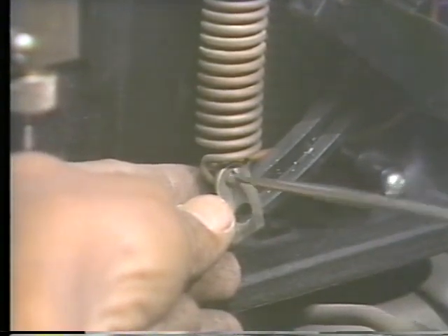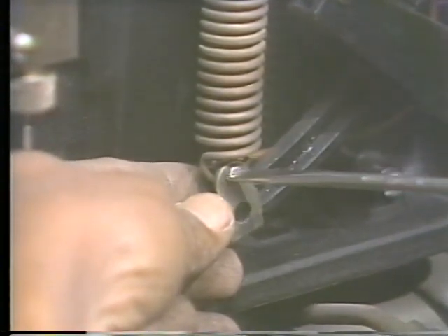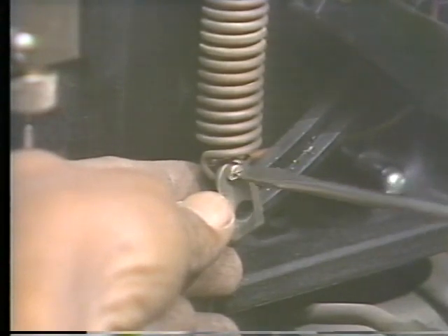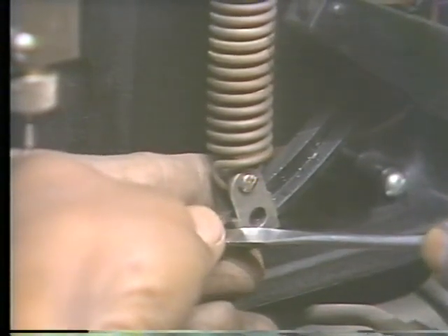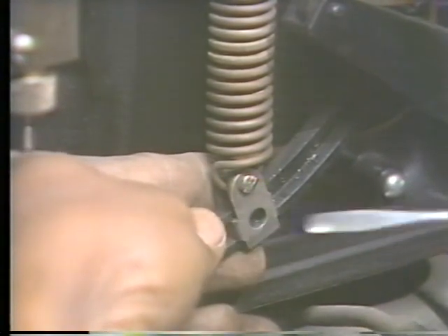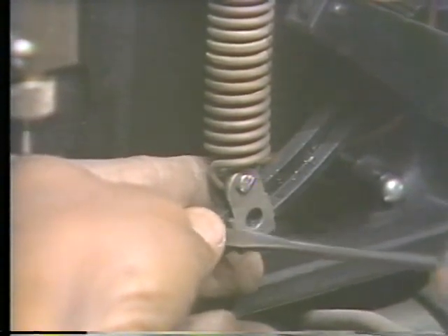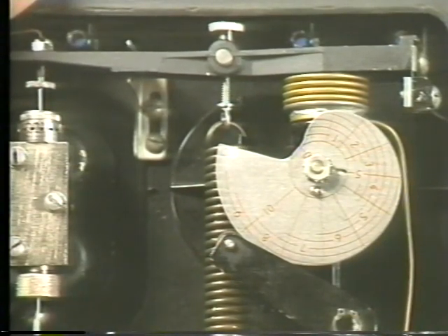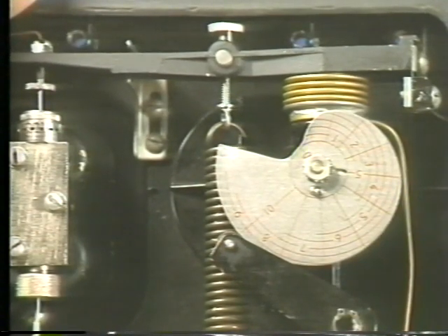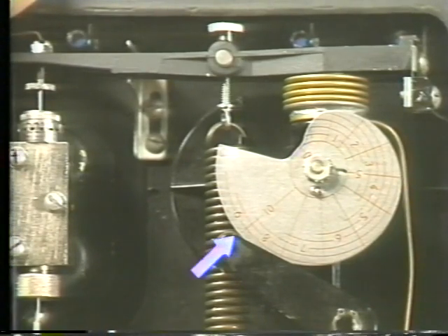Even if the cam doesn't move when the beam is lifted, the cam should still indicate 10. This adjustment is made by loosening the range adjustment and moving it along the spring beam until the cam indicates 10. Then lift the balance beam again to make sure the cam doesn't move, indicating that the piston and louvers are indeed fully opened. With the control air pressure at 27 psi and the cam reading 10, the piston and louvers should both be fully opened.